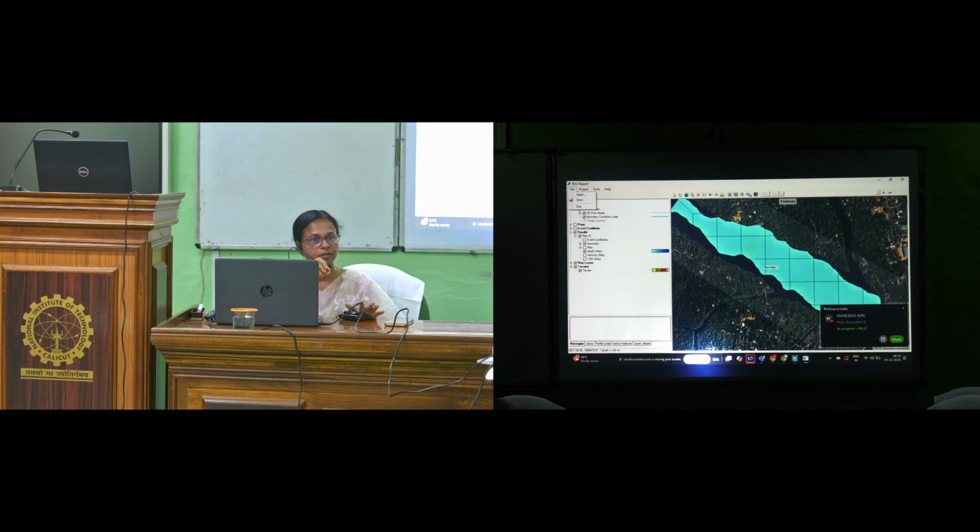Then Manning's roughness coefficient you have to give here again. As I mentioned yesterday, for different cross sections, the water surface elevation will be calculated at each cross section. So you can even see each cross section you have drawn. Then you can manually edit that, or you can import data from your field work and all.